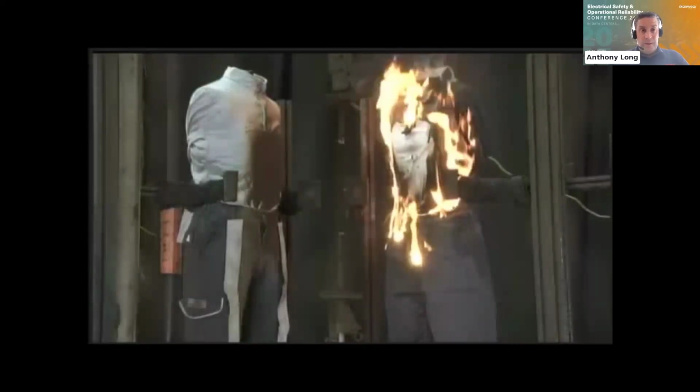And to give you an understanding of this, or to put into context what we're talking about now: if you are wearing a garment which doesn't actually meet the arc rating that you are expecting within a particular unit of equipment, say, for example, the equipment is rated at 14 cal and you're wearing 12 cal, you may be sore as a result of the arc flash.